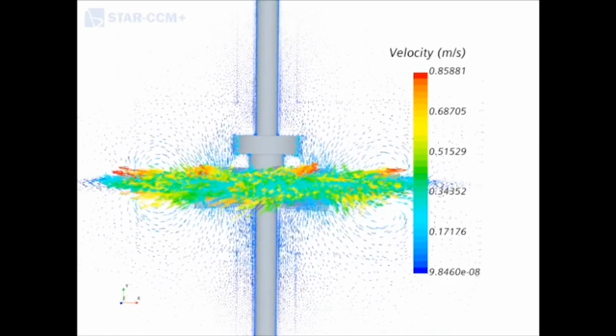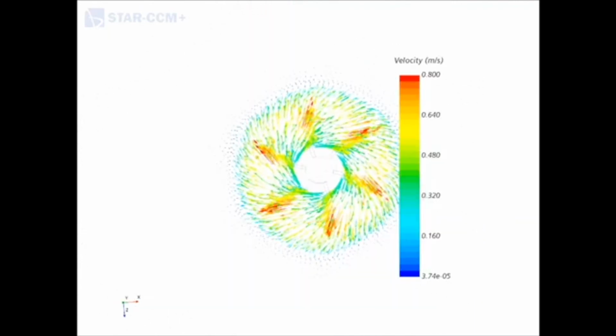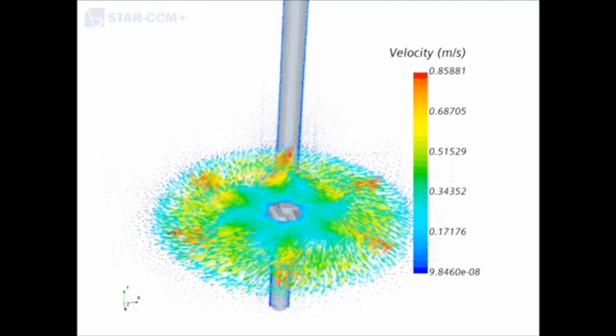On the velocity vectors animations, it is also shown that the flow is not being ejected radially to the walls of the tank as expected. This means that the impeller is not mixing the fluid properly. In order to increase the velocity inside the rest of the tank, it is necessary to add deflector plates, which are necessary for high speed and for improving the performance for both impellers.